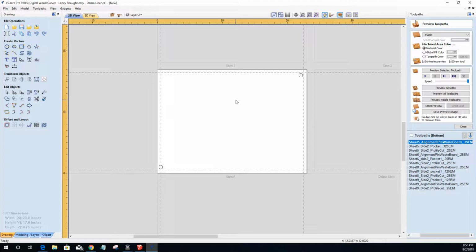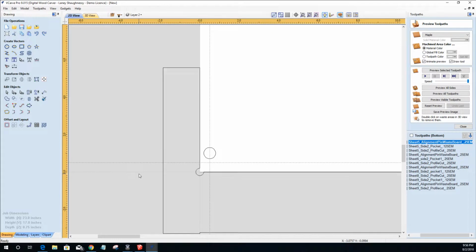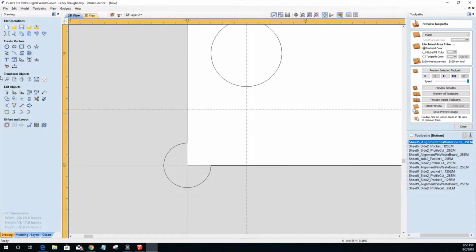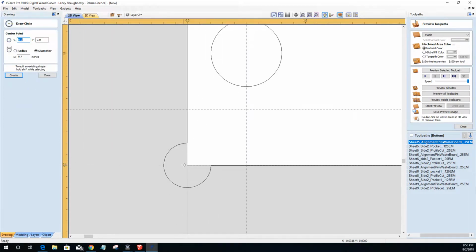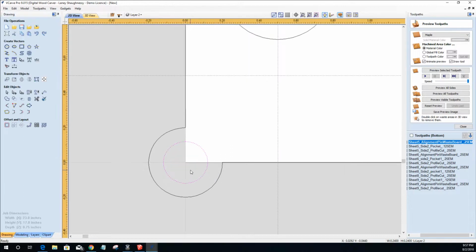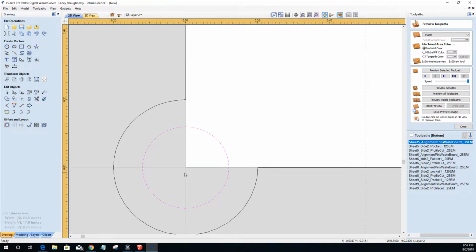On X and Y alignment with a different size end mill, how do you ensure that you are at X and Y? All right. So, William, the center of the router bit is zeroed out over the corner of the board. This pink circle represents a bit in my corner of the board. This is zeroed out on the center.